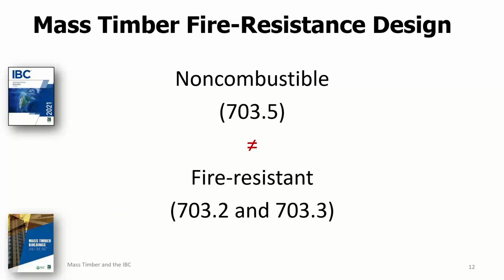All right, now let's back up and look at some even more basic and more generally applicable principles related to fire safety, specifically in the context of the IBC. Non-combustibility and fire resistance are two very different things. I want to impress that upon everyone here. They each have their place in the code, and the code requires non-combustible materials for some purposes and then specific fire resistance ratings for others. So they're both very important concepts, but they're very different concepts in terms of fire safety. Some non-combustible building elements have little or no fire resistance because although they may not burn, they still lose their strength rapidly upon being exposed to fire.